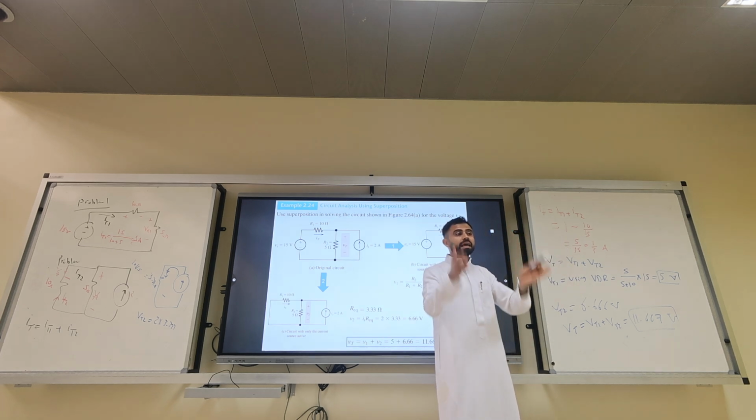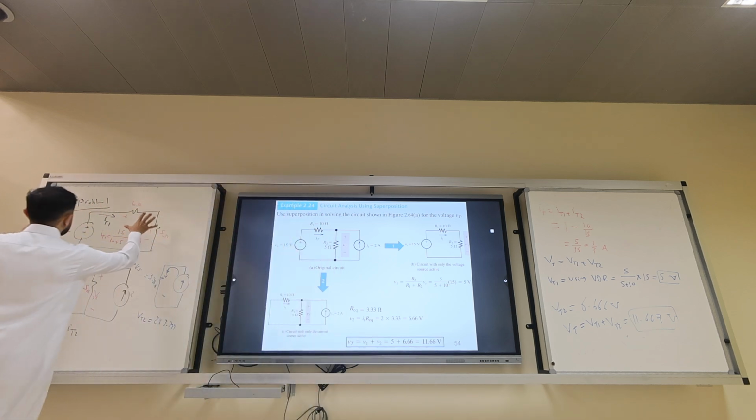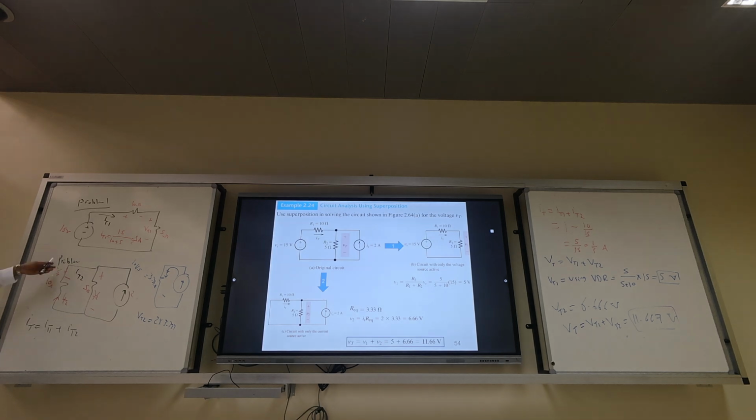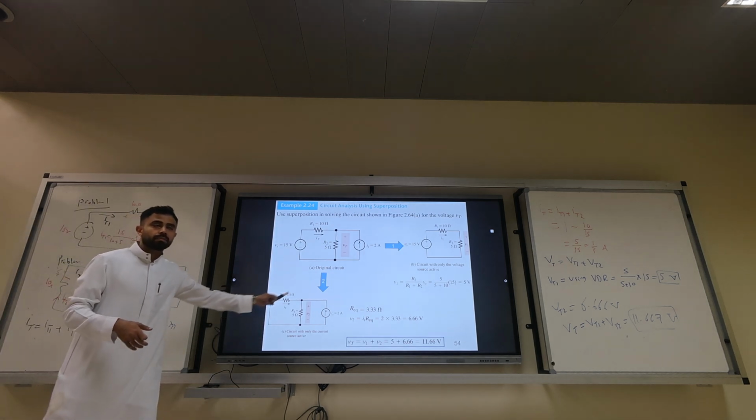Now, again, we still have a problem with many students. Once they see this circuit, they say, oh, what is IT1? Okay, then it's 15 over 10 plus 5. For that circuit, what is IT2? It's the current that goes through this resistor from bottom to top, and I told you to put plus and minus the polarity to avoid the passive sign configuration because you already wanted that current. If you redraw the circuit, IT2 is the current that goes from bottom to top.